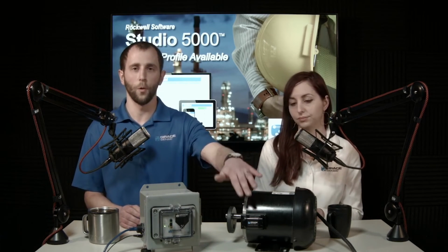Yeah, so we do have the ability to cable out as well, via either the gateway or the VBT, using coax-type cabled SMA connections. Maybe you have one remote VBT that's off to the side that you'd want to bring in. Maybe it's under guarding and you want to get that out from under the guarding, because a metal box around a wireless system does not perform very well. So we want to eliminate that Faraday cage. Or the gateway itself: if you had it in one location where you already had power and Ethernet run, and you want to just pipe out one coax cable to go and pick up those VBTs, you can do that. So it can get around some of those RF issues.